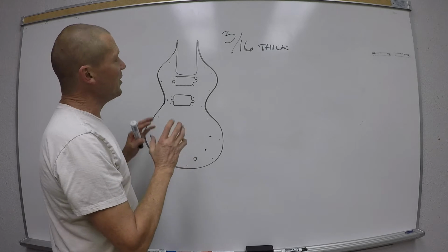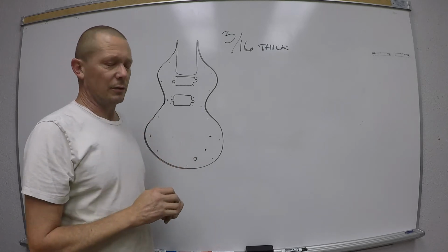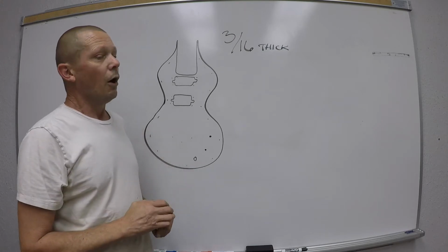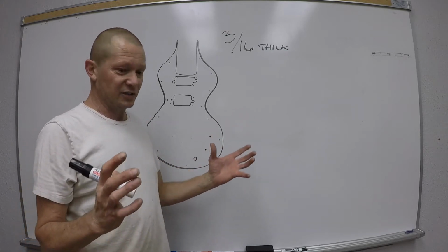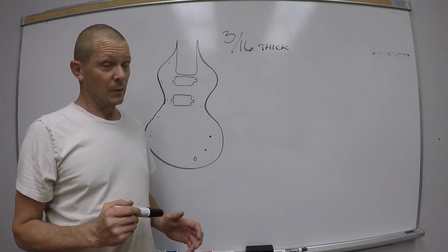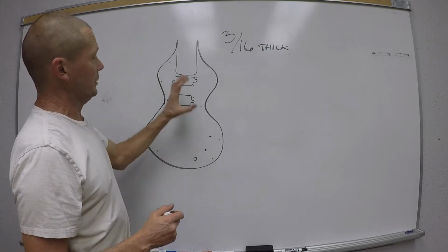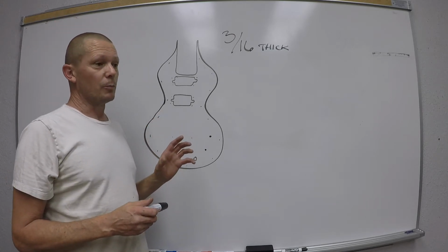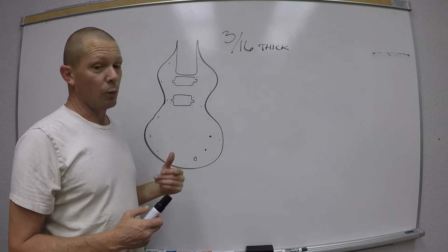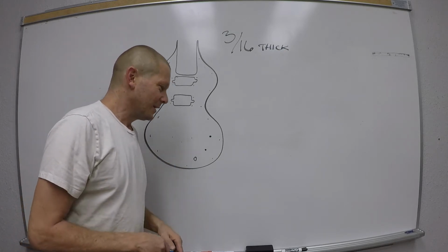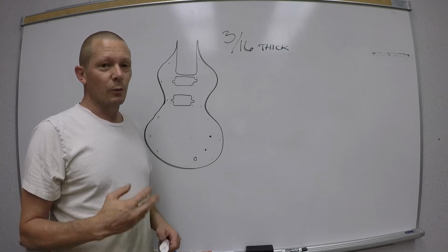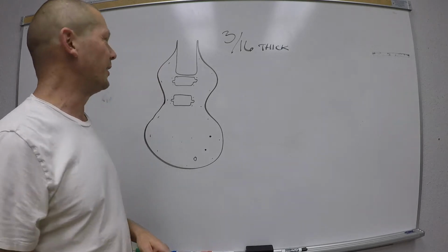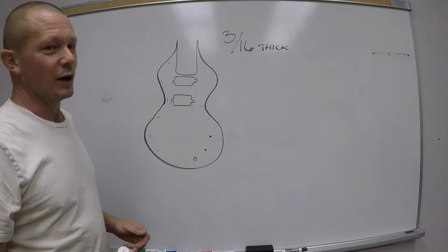Not always, okay? And things move. Even though you think, no way, you've got all that vise pressure and clamping force, these hold down fasteners and jigs, things move. And if we get our holes in before things move, then there's a much higher chance that the part won't end up in the recycling bin. So when at all possible, no matter what you're doing, wood, anything, you always drill your holes first. Okay, there's the tip of the day, even though I've mentioned it before quite a few times.